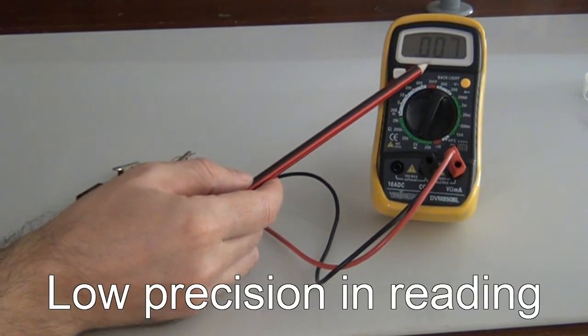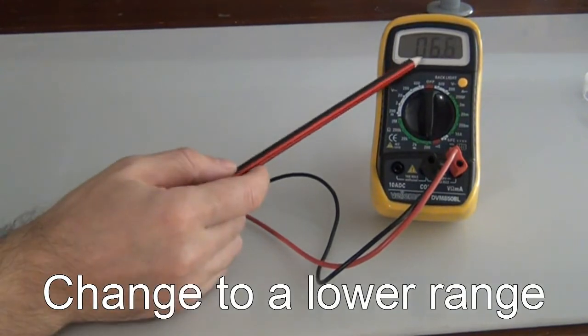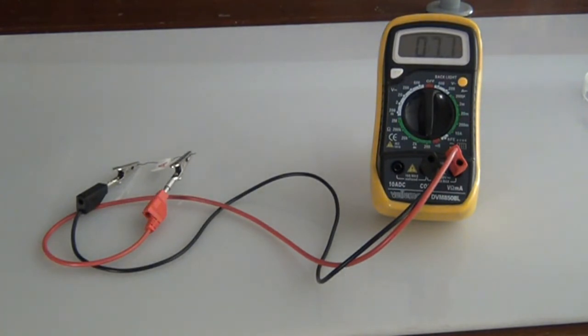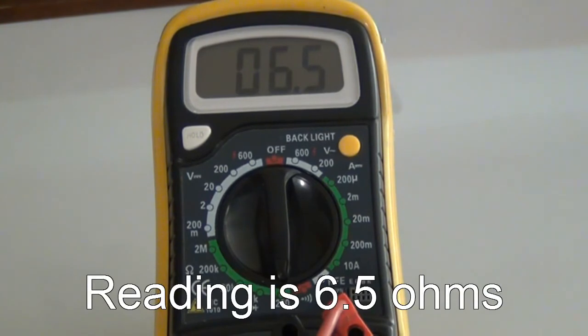And we can see that it has low precision in the reading, so we will rotate the switch to a lower range to read better. So we can have a better precision in the value. And we read that the value is 6.5 ohms.